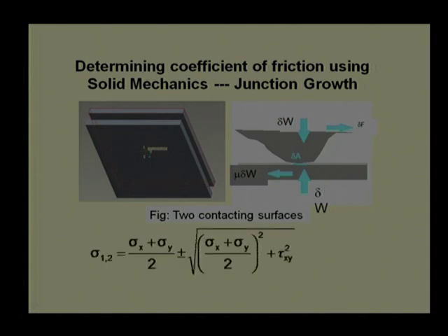Now, if I take the help of principal stresses or use solid mechanics to derive the relation, what we can get is principal stress 1, principal stress 2 equal to the average of stress in x direction and stress in y direction, plus minus, plus for sigma 1 and minus for sigma 2.